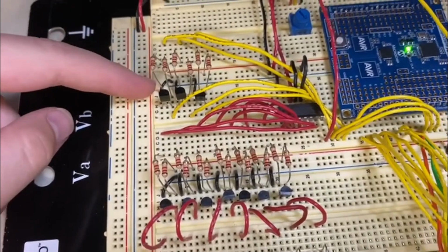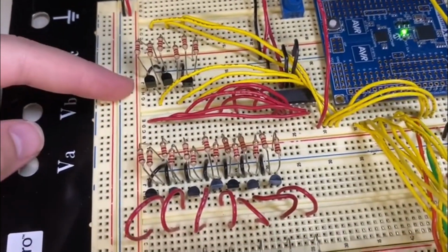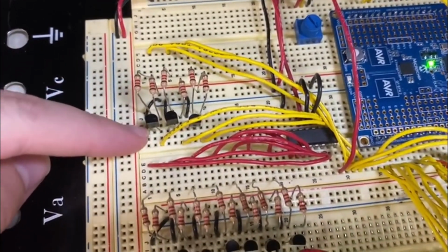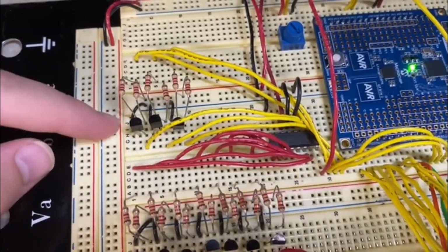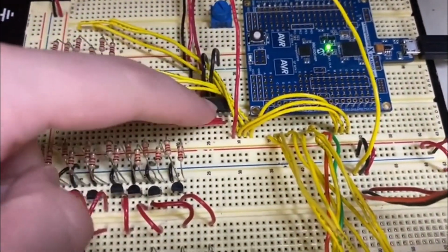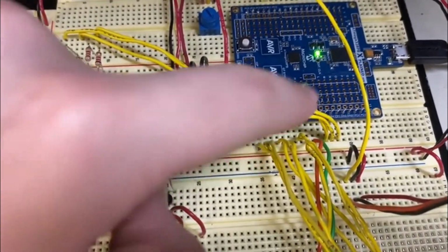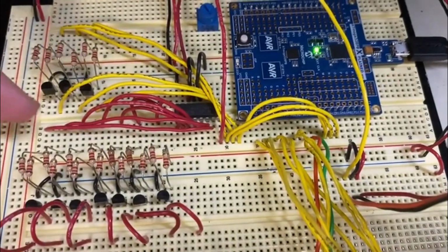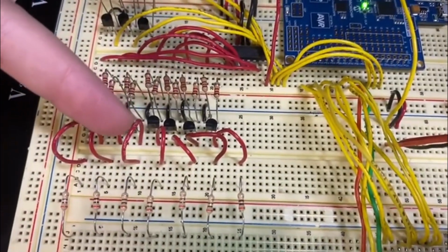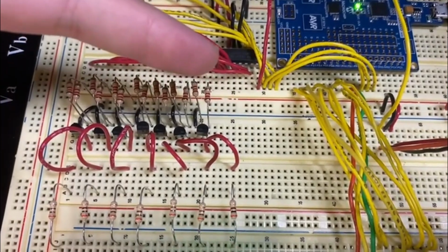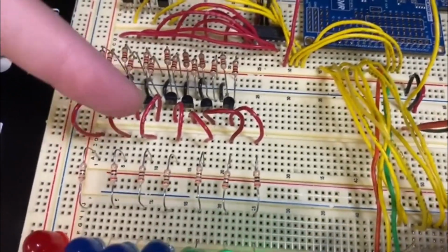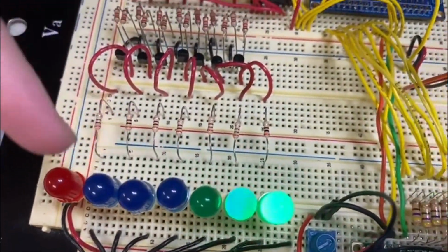And because we did not have NOT gates, we had to create NOT gates at the transistor level using 1.2K ohm resistors and some NPN transistors. And as such, these outputs from the 328 are grounded, which allows them to be sent to the decoder, which then those outputs are then also inverted, because whenever they are sent out from this decoder, they are grounded. So we want them to power the LEDs, so we have to invert them again in order for them to power on the proper LEDs.